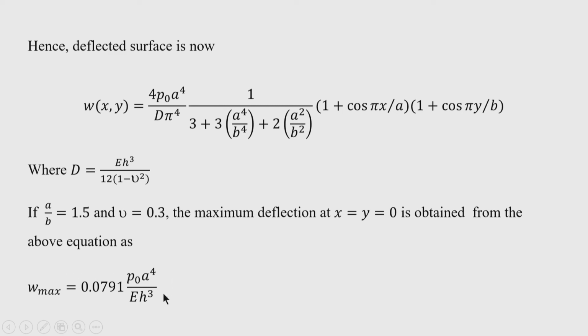So, the slight variation of the deflection will not cause any difficulty for practical applications, but we have to see whether the second and third derivatives, which are used to find the bending moment as well as shear force, retain the accuracy or not.